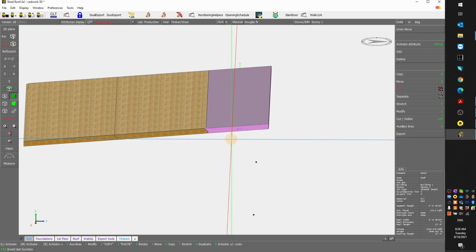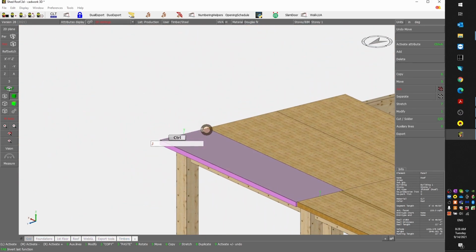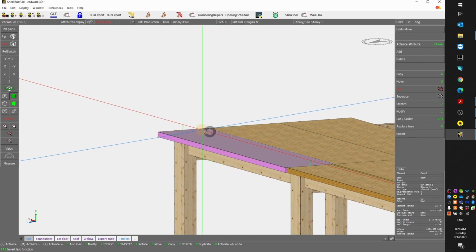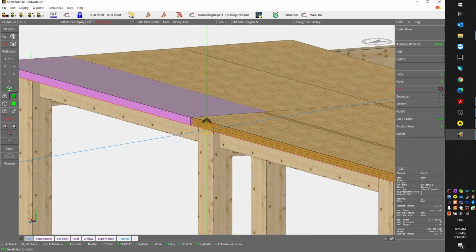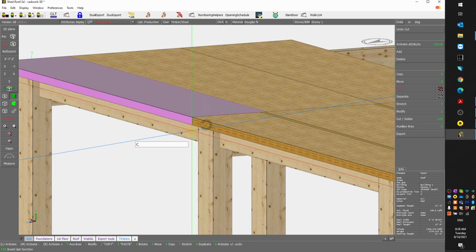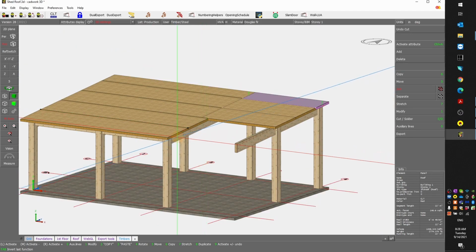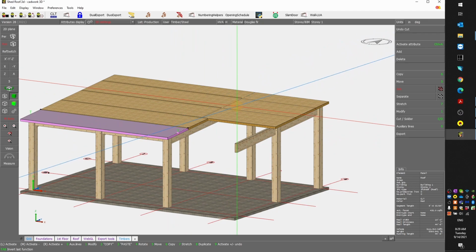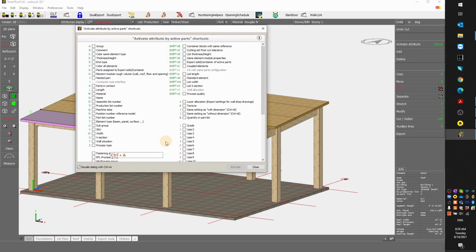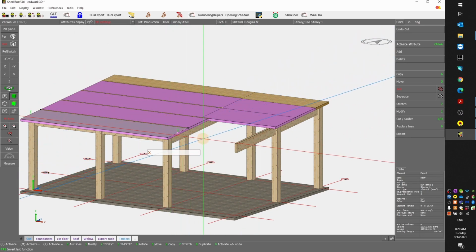So now I can press J, and I see that I can cut the panel. So I left click on the panel, press C to cut, and click on the face. There we go. And now I can make sure that all my panels, well, most of them, are 10 feet wide. I can select one, do Control A, X, and I see that all these guys are 10 feet wide.